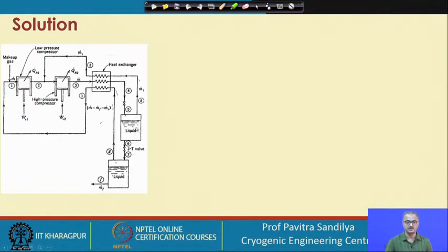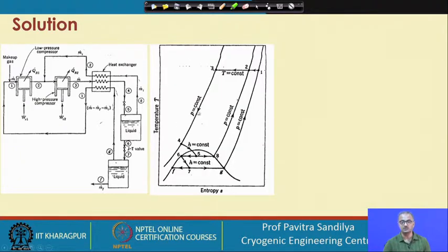The first reservoir is simply sending the cold vapor back, and the second reservoir is from where we are getting the liquid. This particular thing we have to keep in mind, and we showed this earlier. That's how this whole process can be represented on a TS diagram, and this is an ideal diagram where we are neglecting all kinds of heat losses and the changes in the kinetic and potential energies, and based on all this we generated this particular curve, which I am not going to discuss now.